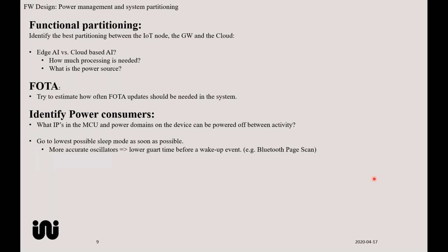Then you should go to the lowest possible sleep mode as soon as possible. Most MCUs and application processors will support a variety of sleep modes, and the difference between those might be wake-up sources. Typically, can you wake up on an interrupt on a GPIO pin, or could you wake up on a watchdog timer, or can you wake up on the RTC? So you need to select the one that is most appropriate for your system.